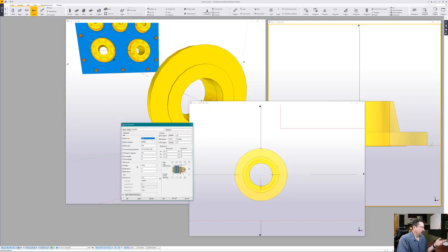The tolerance we want to change, for the hole itself. Since we are drawing the hole, I want the tolerance of the hole to be 0 because I want it to be a 3/4 inch diameter hole. I don't want it to be set up for a 3/4 inch diameter bolt. I want it to be a 3/4 inch hole. So since my bolt size is 3/4 inch, my tolerance would then be 0, which makes my hole 3/4 of an inch. So we got that.